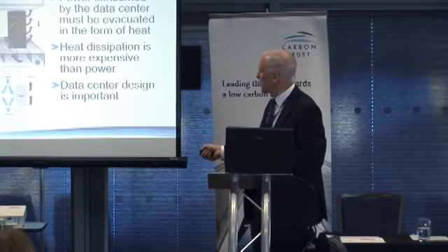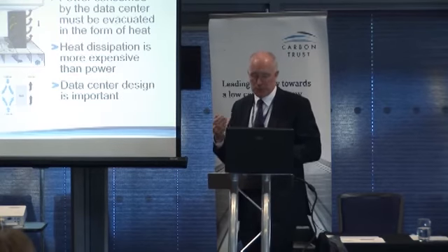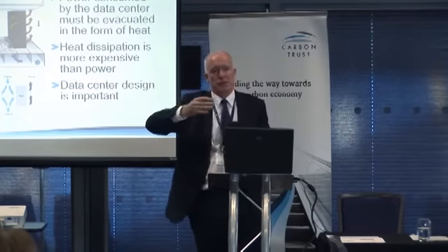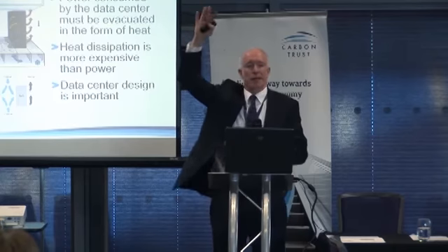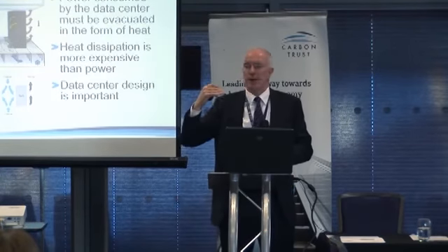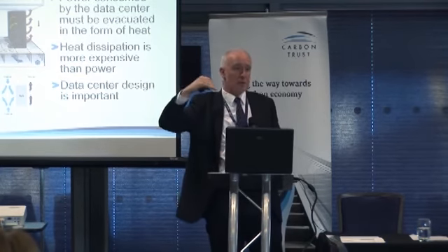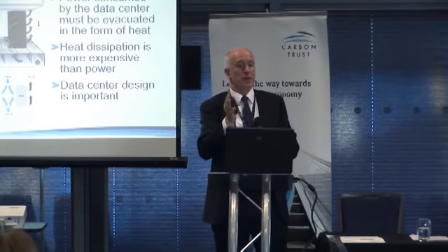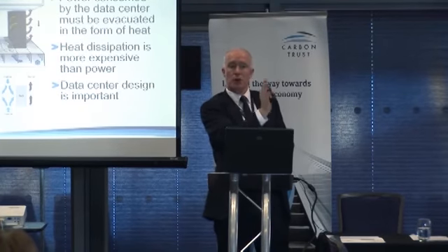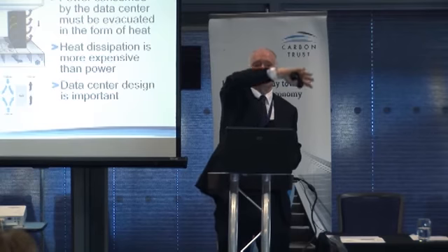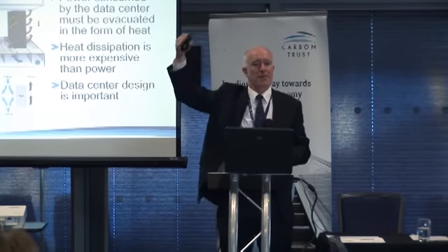And so you've got this sort of concept where you've got the cold aisle rack and the hot aisle, so each rack faces each other with it on either side, and then things become much more efficient. In practice, some of you will find that when you go into your computer rooms, it'll be a small computer room with a direct expansion cassette in the ceiling, or a wall-mounted unit blowing out cold air. Do recognise what we're trying to do is say, well, let's put our racks sensibly so that the cold air blows down to low level so we get the cold air onto them. The other side will be hot. You don't want to mix them up. You want to make sure that the cold air is going onto the on side. At least the hot air then, at worst, can escape in the hot area and come back to the unit. But we're trying to make it valuable, that cold air.